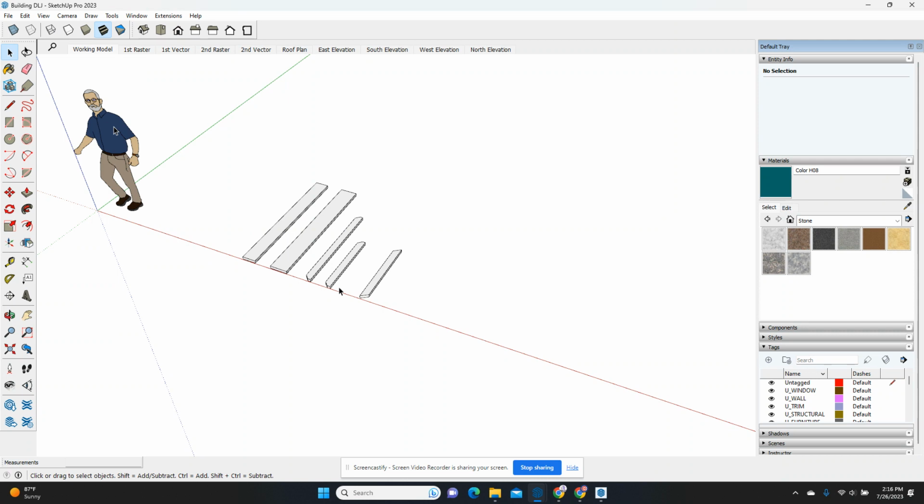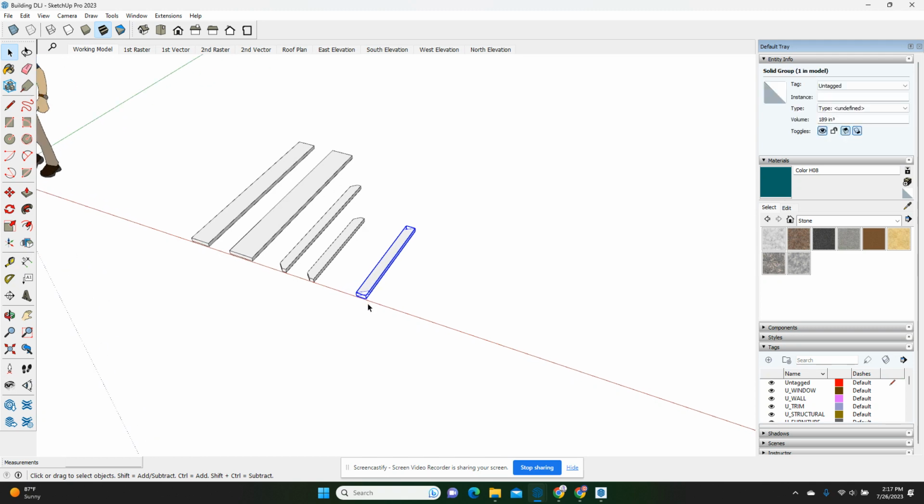I'm going to start to construct my picnic table now. I still have a couple elements that I haven't drawn yet, but we'll draw those once we get this partially assembled. I'm going to be doing several rotational steps, so I'm going to take these elements and rotate them in multiple directions to get them located as I like. It's important that you pay attention to the color of the protractor when I'm rotating. And remember that if I want the protractor to be blue, I push the up arrow. If I want it to be red, I push the right arrow. If I want it to be green, I push the left arrow. So let's get started. Let's select our leg right here.